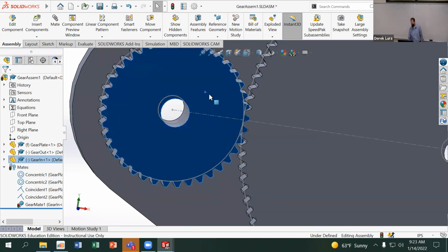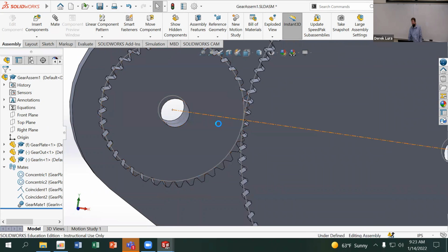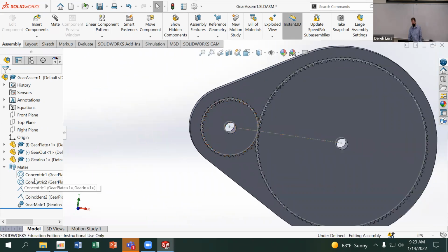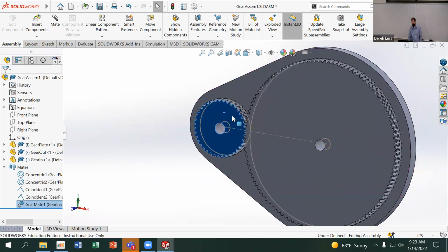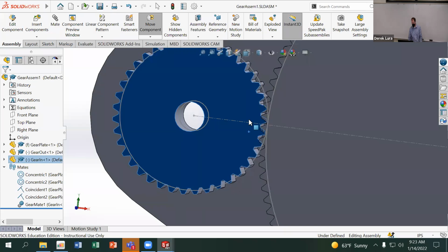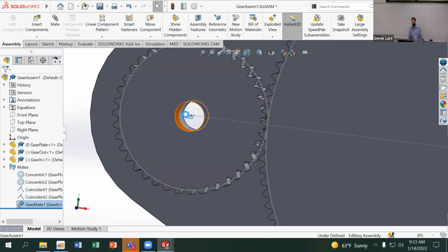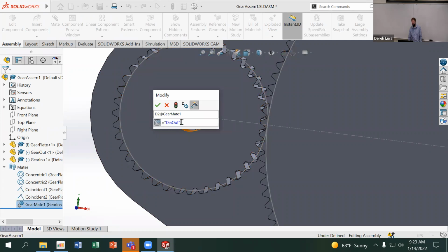Still doesn't seem to quite be rendering properly. Maybe I had it right the first time and it just didn't look right because the gears weren't lined up. The gears should stay reasonably well meshed. They shouldn't slide through each other like that. For some reason, it's not giving me the right values on here. Maybe I just need to hit rebuild before I did it.